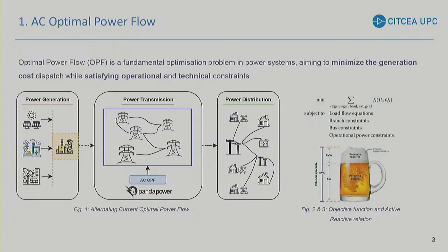I mean, if one generator can give between 10 and 350 megawatts, it will use the center point. Pandapower not only gives us the power injections of active and reactive power, it also gives us the voltage magnitudes and angles of all the buses, and helps us model the network, changing some parameters of the components. This is important for this study.